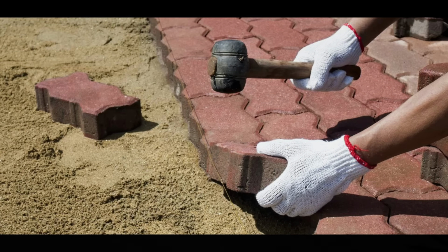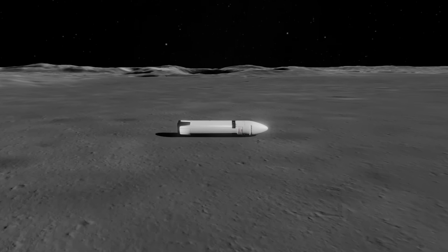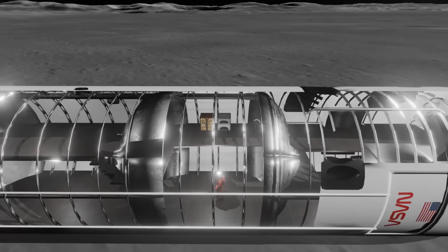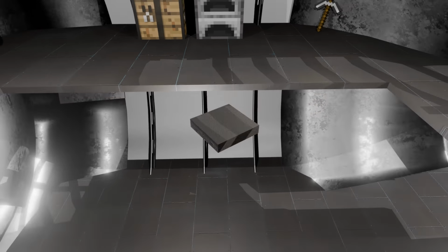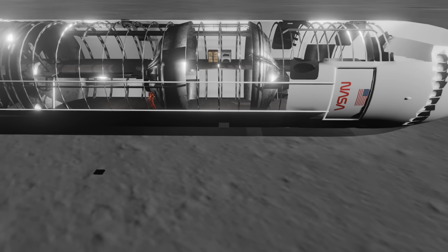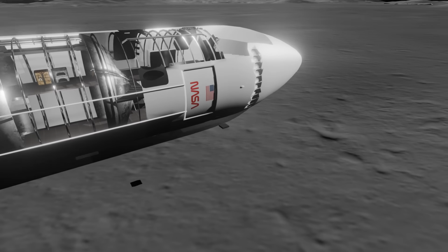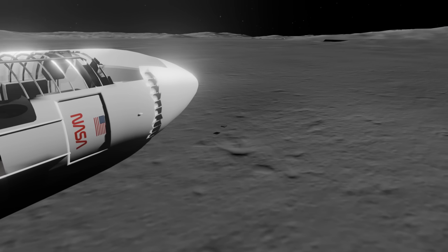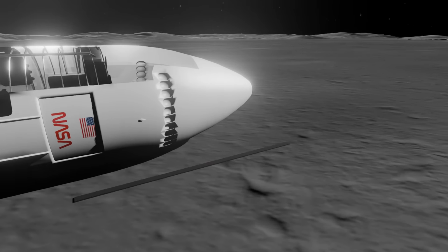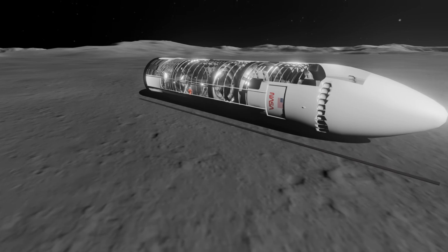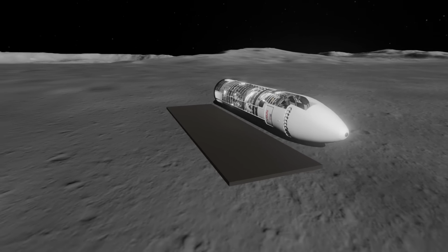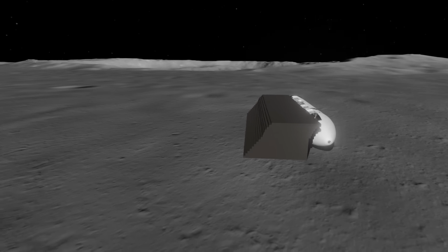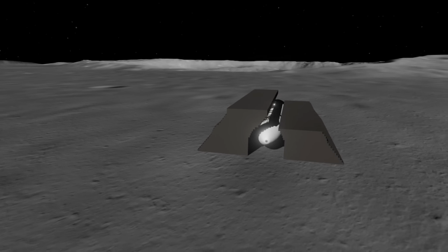The first thing you're probably going to use bricks for though is to create a radiation shield around your retrofitted wet workshop. It needs to be about 3 meters thick on all sides, including the top, which is going to mean it'll be quite heavy even in low lunar gravity. This weight means it's not as easy as just piling dirt onto your habitat. You're going to need to distribute that weight. Fortunately though, we have over 2,000 years of masonry knowledge to tap into to solve some problems.